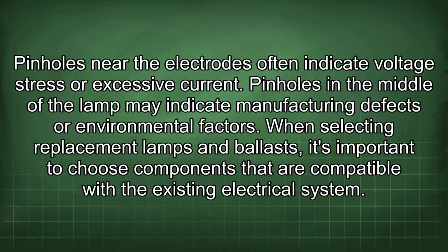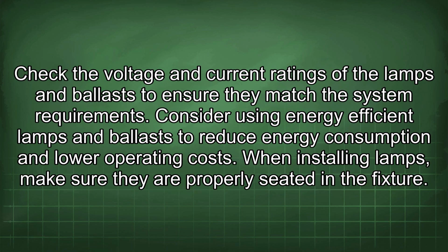Pinholes in the middle of the lamp may indicate manufacturing defects or environmental factors. When selecting replacement lamps and ballasts, it's important to choose components that are compatible with the existing electrical system. Check the voltage and current ratings of the lamps and ballasts to ensure they match the system requirement. Consider using energy-efficient lamps and ballasts to reduce energy consumption and lower operating costs.